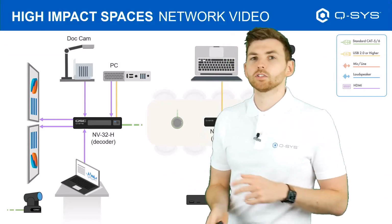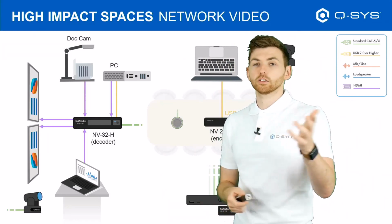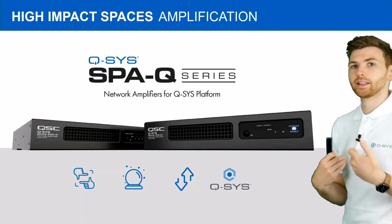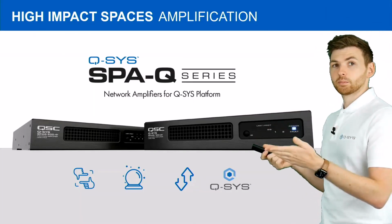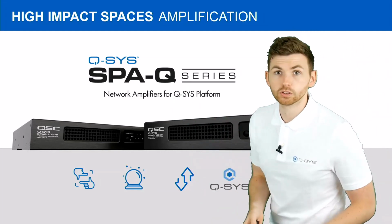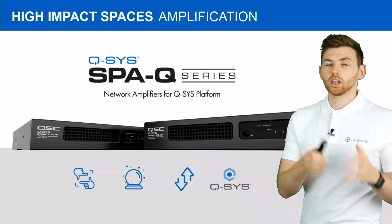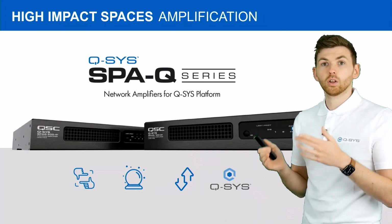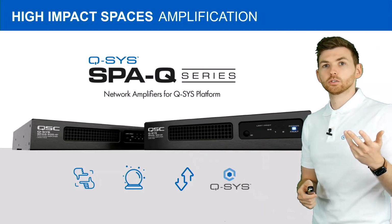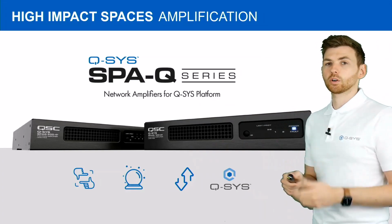So then we might go back to the traditional approach of using a 100-volt line with lots of 100-volt ceiling speakers. So for that, we've got amplifiers, of course. We've been making amplifiers for over 50 years. This is the most recent addition, SPA-Q, small power amplifier, Q for Q-SYS, because this is a 2-channel or 4-channel amplifier that can do low impedance or it can do 100-volt line. And it's also a Q-SYS peripheral. So just like all the other Q-SYS devices we've been talking about, it's programmed in Q-SYS Designer, controlled and managed by the core.